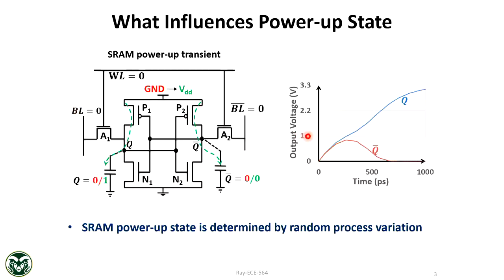Question, yes? If you do that a lot, then it would wear out the whole SRAM faster, right? Yeah, so a little bit is good enough. You're right, you cannot overdo it, then your noise margin and everything will start to suffer at some point. We did some of those experiments. We find the DRV, specifically the data retention voltage, becomes higher if you do this imprinting. That's a good question.